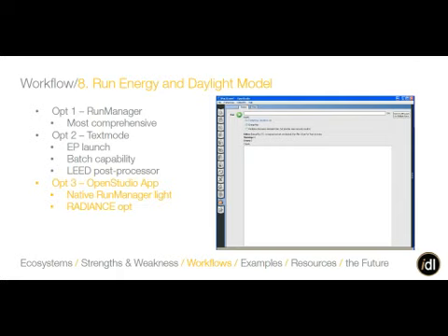The only main difference between these different options is the way that it organizes the output files, which is frustrating because it should be consistent. But these will go a little bit deeper, a couple of different subfolders when you're running in post-processing, because it has to translate OSM to the IDF, then it spits out like 15 output files that you can then post-process. When you run in Textmode, they all just come at the highest level of where the IDF was located. So there are some idiosyncrasies between where it puts those files.